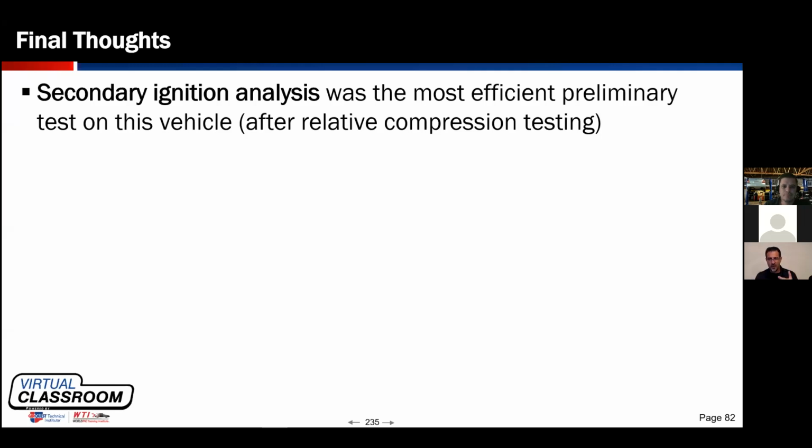If I put in a spark plug that was not fouled, the engine began to run normally. When I say normal, I mean it performed normal. It's still going to be consuming some engine oil over time. It might go another 10,000 miles before the misfire returns. I don't know. But the point is, the customer wanted just the spark plug replaced. And now that the car is in seemingly good working condition, it's far easier to trade in at a higher value than it is with a misfiring cylinder.